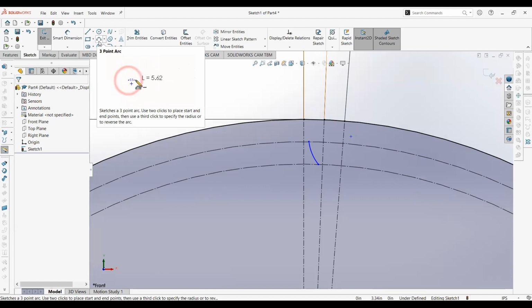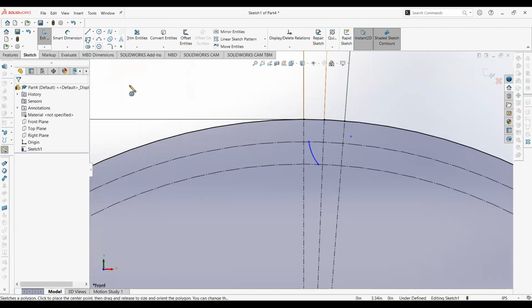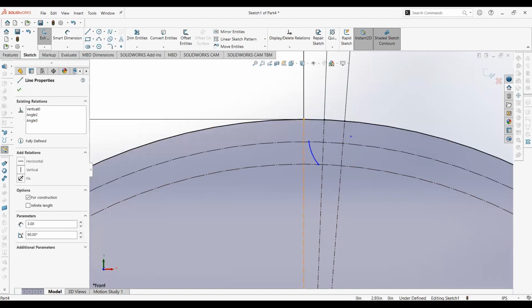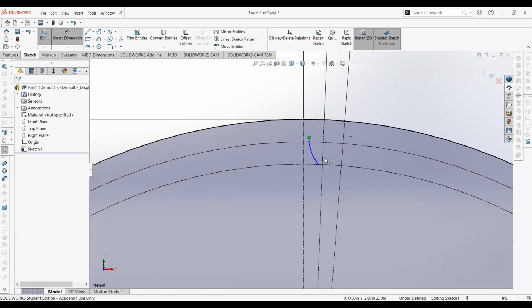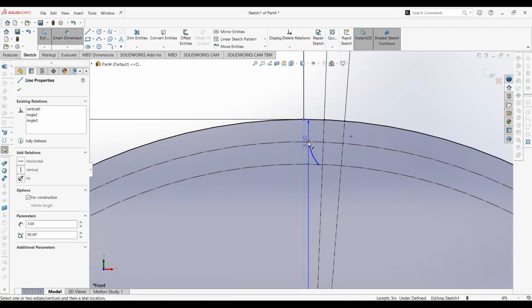Yes, okay. You're gonna do this dimension again. All right, smart dimension. So you're gonna hit the vertical line, right? That one that we've been doing before. Hit there and then not this entire line, but click on just the top corner. You see that dot that's highlighted in orange? Everyone got it? Hit that dot and the line.